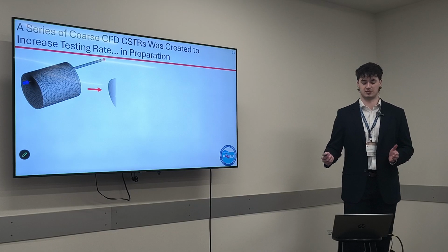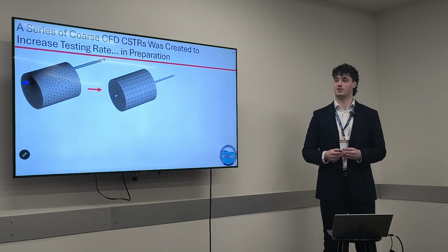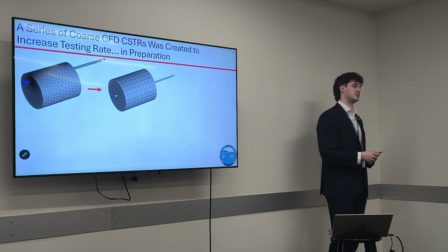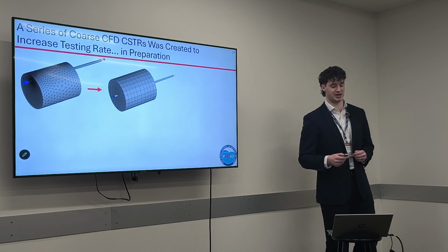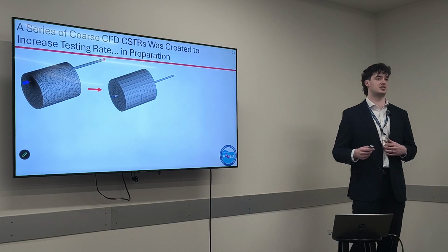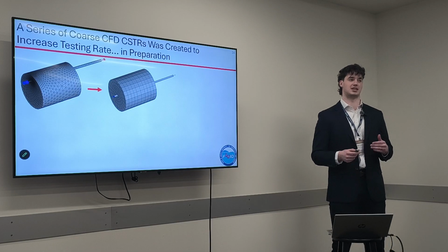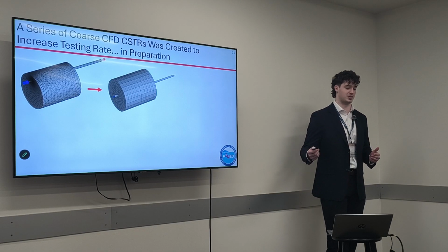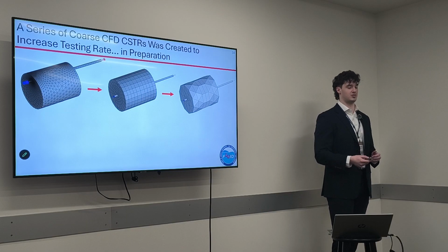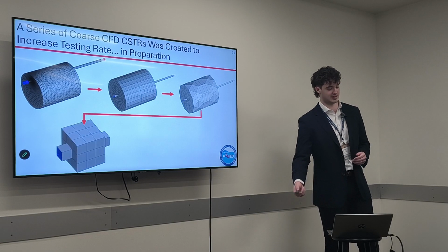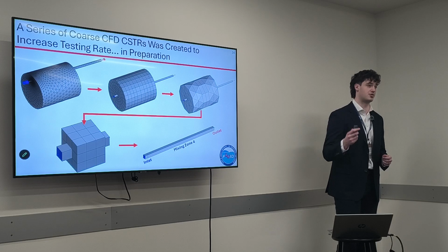So we reduced it down to around 4,100 hexahedral elements, since they're just more efficient with space. And that provided good results, had little effect on accuracy, but sped us up a lot. So we wanted to see how far we can push it. We eventually went down to 1,300 elements, then down to 29, then down to 3.